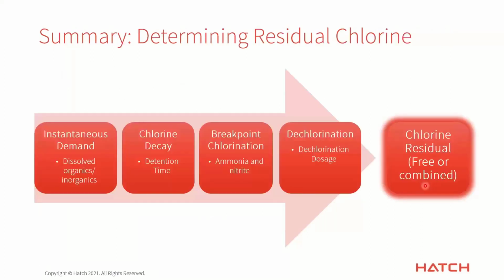All right, so now I'm just going to do a very quick summary of the steps taken by the model to determine residual chlorine, and also remind you of the key factors that affect the residual at each step. The first one is the instantaneous demand, and this is affected by the dissolved organics and inorganics. The second one is the chlorine decay, and this is affected by the detention time.